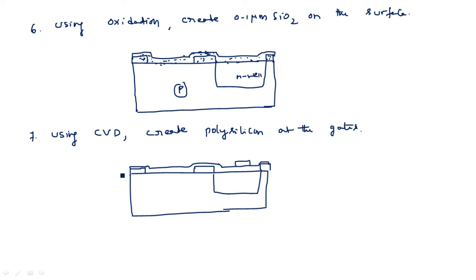So here one polysilicon layer, here another polysilicon layer, indicated by black slashes. Using the chemical vapor deposition technique, the polysilicon is created. Okay. Now remove this particular area and this one. Totally we need to remove 4 areas so that 2 p plus and 2 n plus regions are going to be diffused.